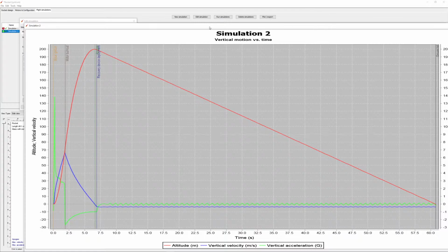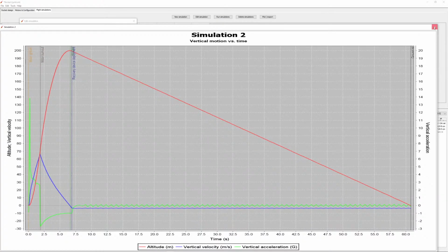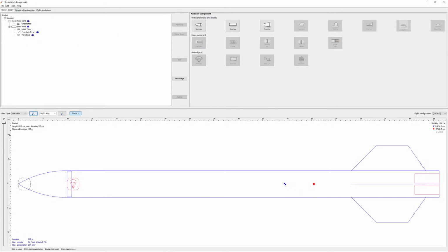And real quick, I'll show you what I mean by a ribbon. So there's the traditional parachute for model rockets, but you can see here there's also a streamer, which is basically when you don't have the mass or you don't want to use a parachute, you can just use a streamer, which will slow you down quite a bit because a streamer or a ribbon is not super aerodynamic.